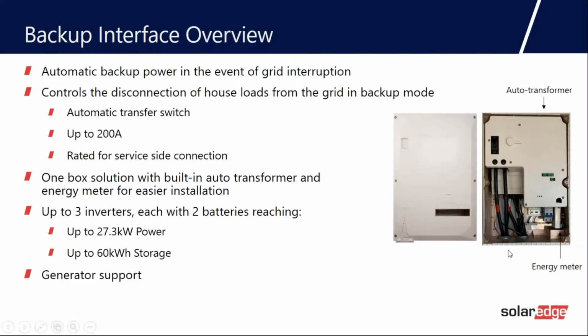Also in here, you can see there's a DIN rail that comes factory installed with one 2-pole 40 amp breaker. You can add up to 2 more breakers. You can change the breaker to a 60 amp breaker when we get to the 11.4, but that's where all your solar breakers are going to land.